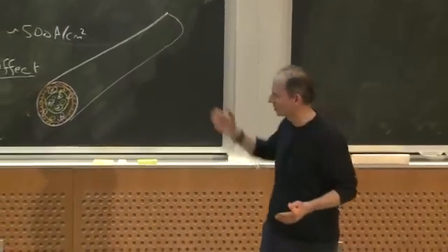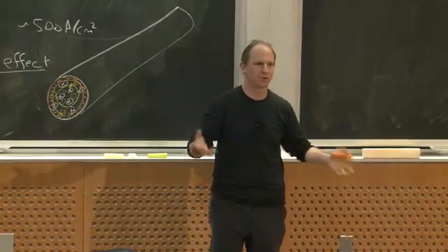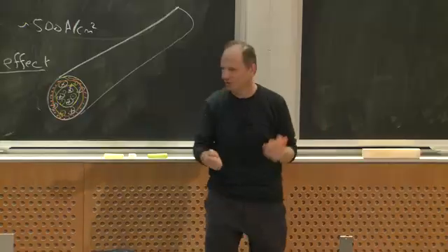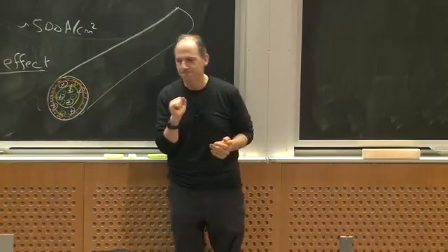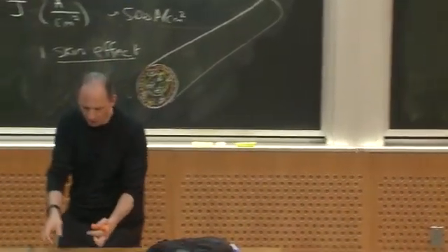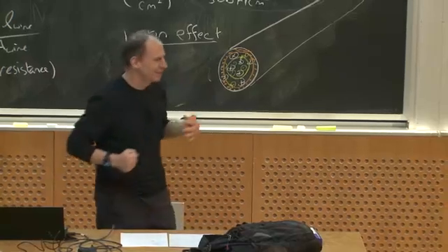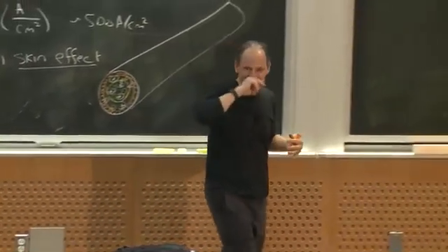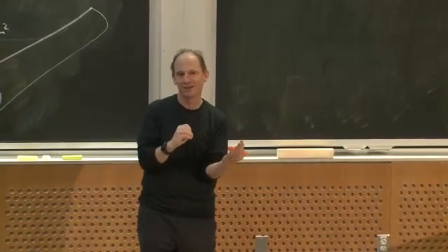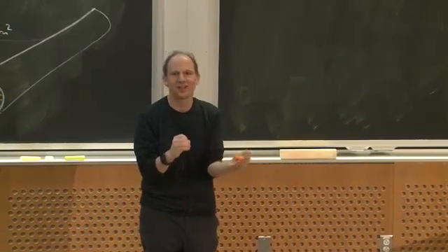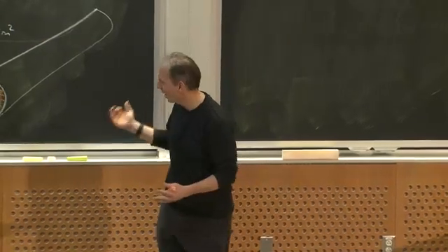Why does this happen? It happens exactly for these eddy current reasons. To actually solve things, you generate what's known as a magnetic diffusion equation. You solve it, and you can solve for the current density profile going in from the surface of the wire. This is kind of annoying, because I've got a certain amount of wire, and I wanted to use it to carry current, and now if the frequency is high enough, I don't get to use all of the wire, and I've just got this dead space in the middle of my wire that I'm not getting to use.